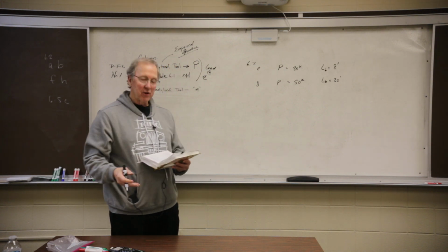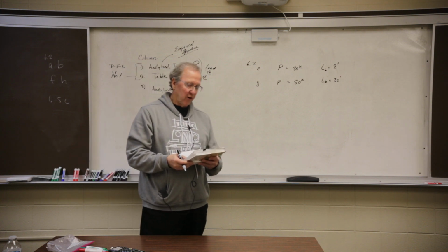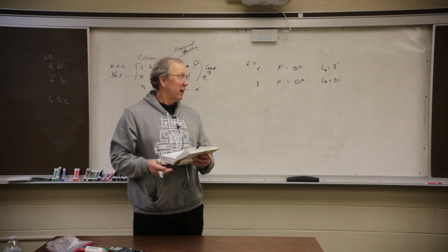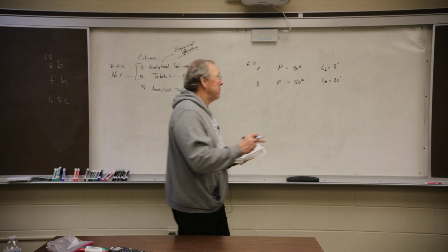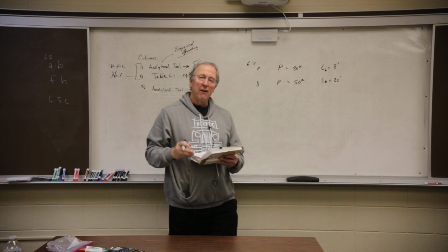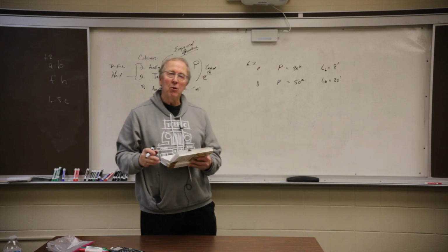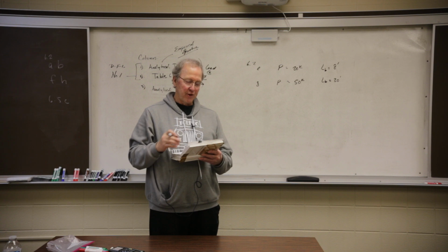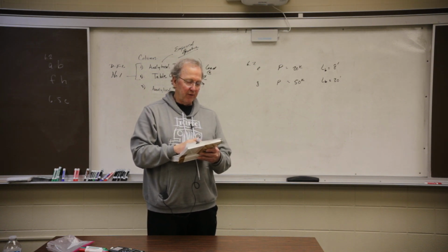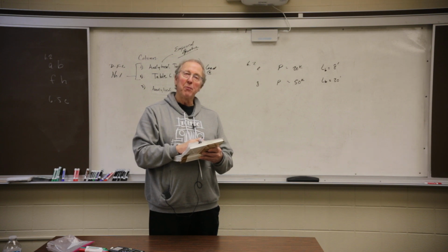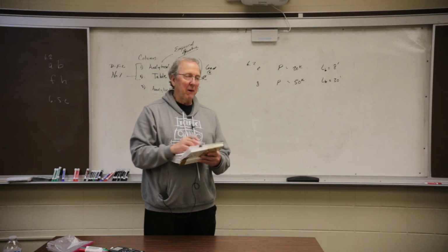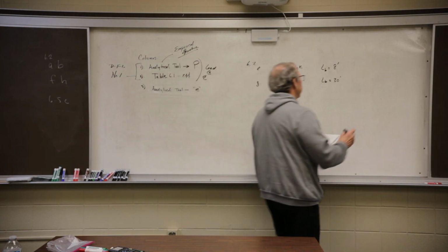Okay, here's all you do. Turn to page 244 and turn your book so you can read the table. Okay, what I want you to do is put your finger on 8 feet. Wander down until you hit the first number that is equal to or a little bit larger than 20. 7.28, 11.4, 15.1, 24.8, first number. Go to the left, 6 by 6, write it down, and you're done.